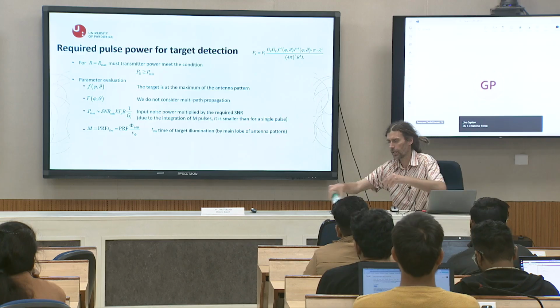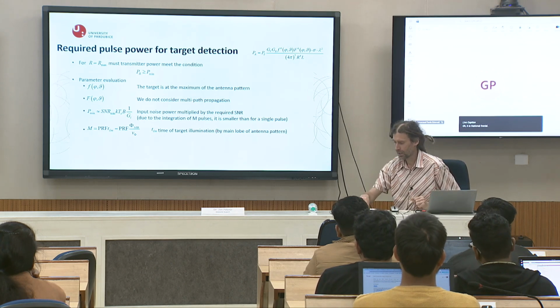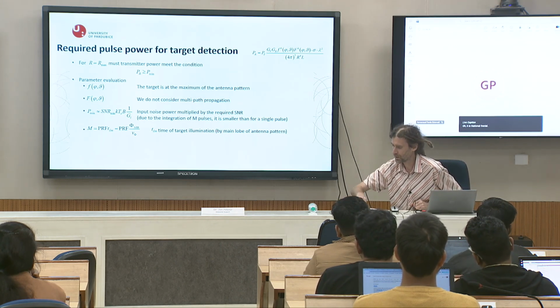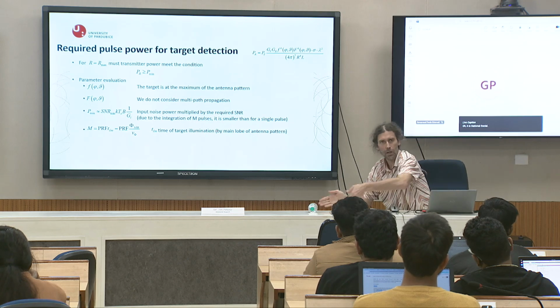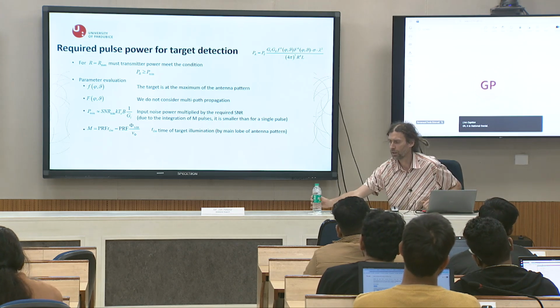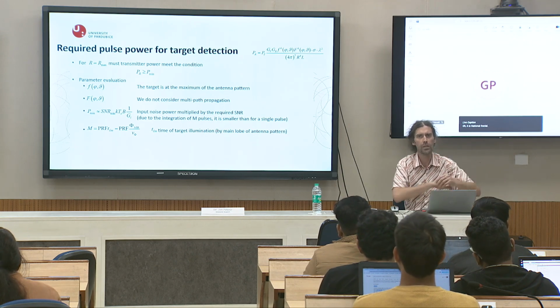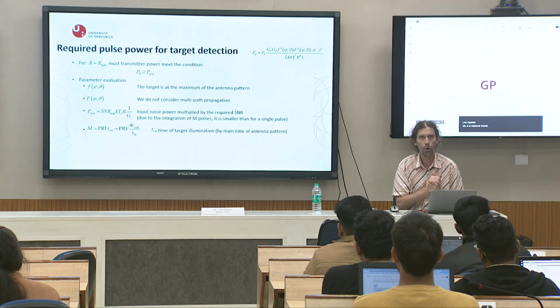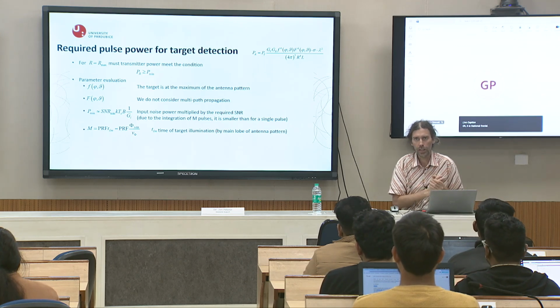Imagine that this is the target and there is the radar, and I send one pulse, second, third, 4, 5, and 6 is outside of the target. So I will illuminate the target maybe by 10 pulses, 100 pulses. It depends on the shape. Of course, more pulses, more information, more reflected energy.